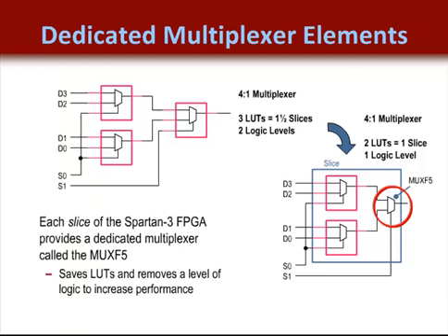You can't just group any lookup tables in this fashion. Likewise, there is dedicated routing associated between the other MUXs to create the faster and larger multiplexers. So you can't just separate these resources out. You have to use the ones associated with a single CLB. Finally, be sure to use your schematic viewer to make sure that your synthesis tool infers these resources correctly.